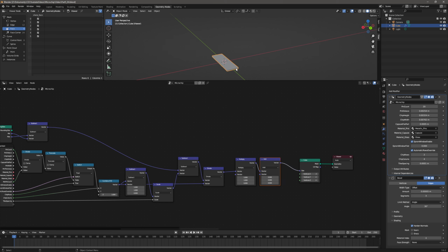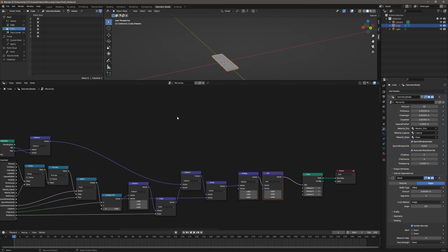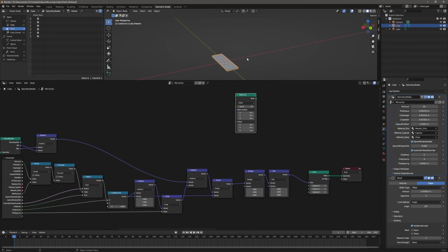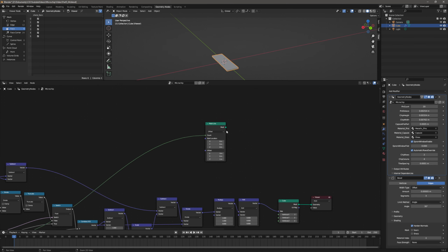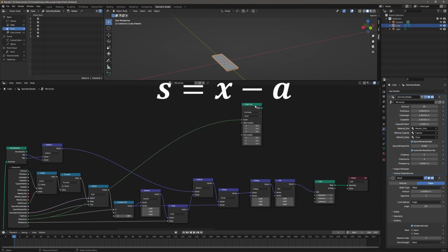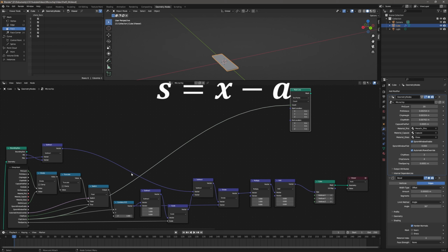Now let's make the points on which the instances of the tile will be placed. So I will use a mesh line for that. Let's add here that node. And first one will be the columns on the x-axis, so first, second, and third. So let's plug the chip columns to the count input of the mesh line, change the mode to endpoints, and the end location will be actually the size of the line, which is the size of this bounding box subtracted, and I will subtract from that the size of the tile.